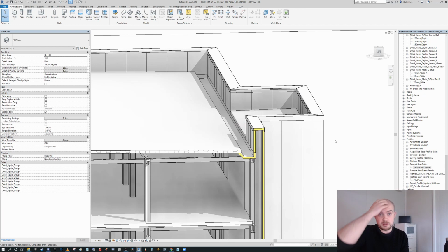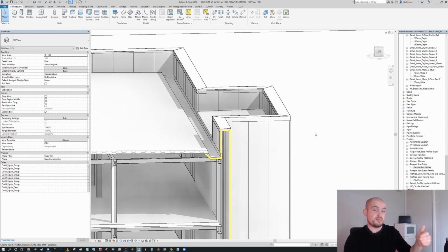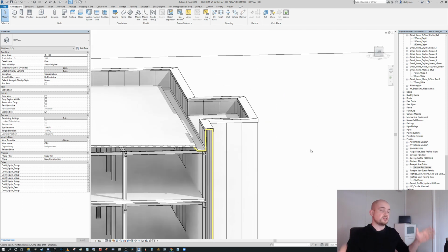And then finally, using the two families that we've generated, I'll be generating a whole video which will go through in-depth a way to actually detail out parapet models properly within the Revit environment, so that when you make a grid alteration, the whole arrangement of the wall, from the rising wall details all the way up to the parapet details, including the gutter and the alignment of the roof, all of that information also slides with the setting out changes that are grid driven. So it's a way of managing the roof detailing correctly, so that when you're changing your GAs on the floor plans for the levels below, you know that your roof integrity is still intact.